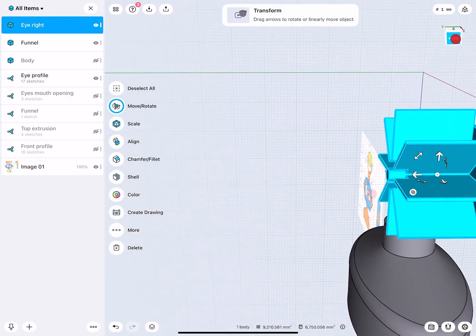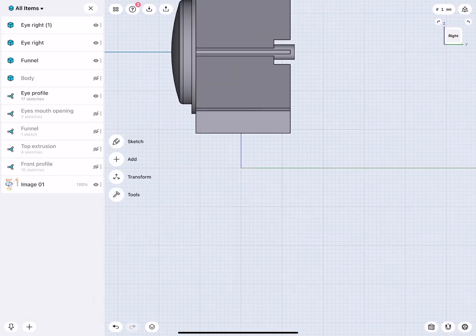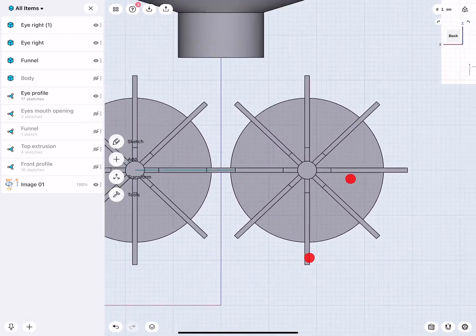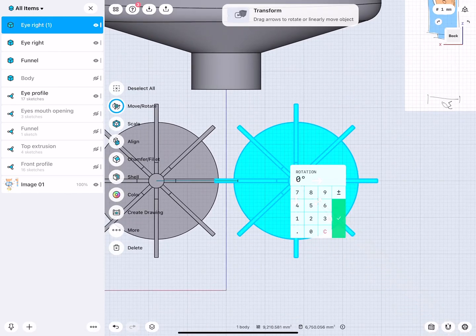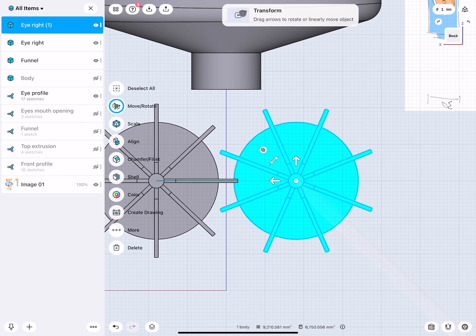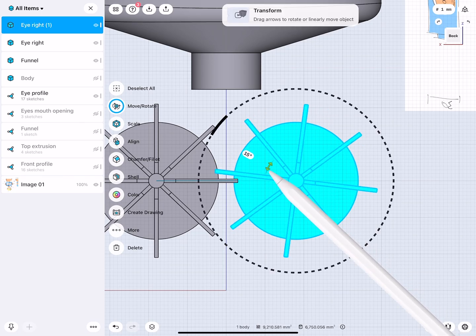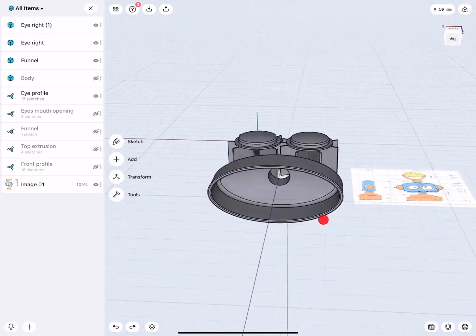Select this eye, go to a side view, mirror. We want to mirror this over. So what's important now is this has to be rotated because the blades are connecting or intersecting. So 45 divided by 2 is 22.5. There, for example. Or who knows really how much this really has to be. This is all based on something to point out later, because the water actually will move these blades. I don't know, so maybe I set this at this rotation.